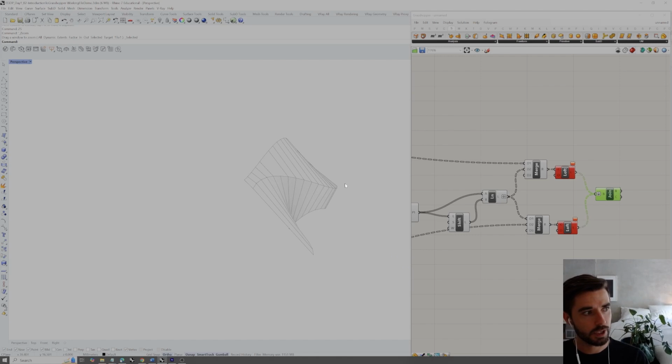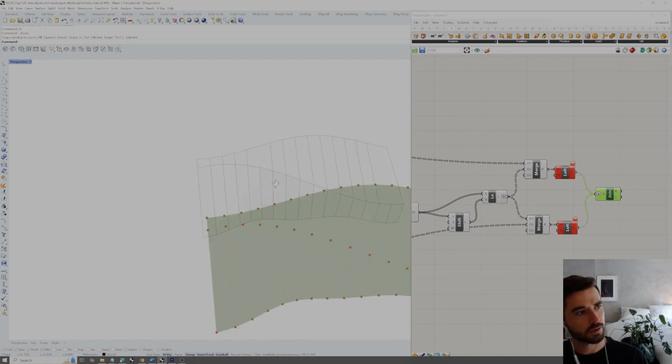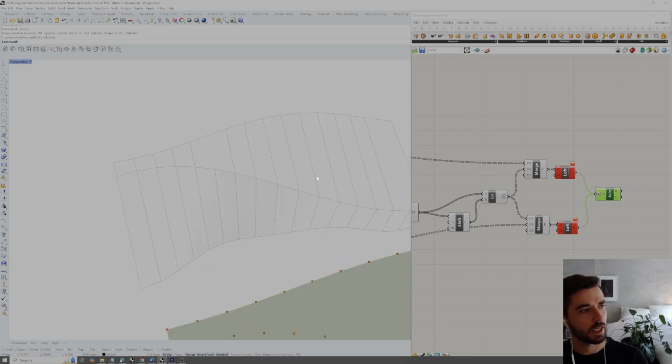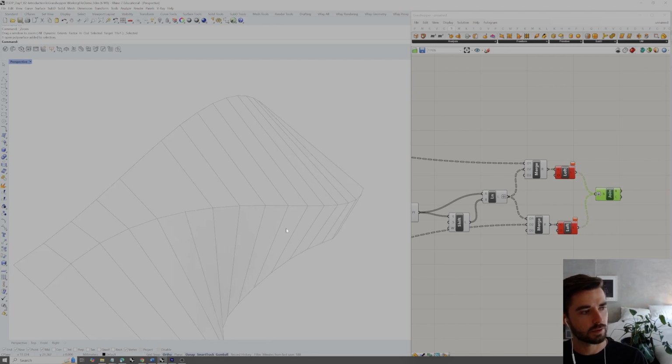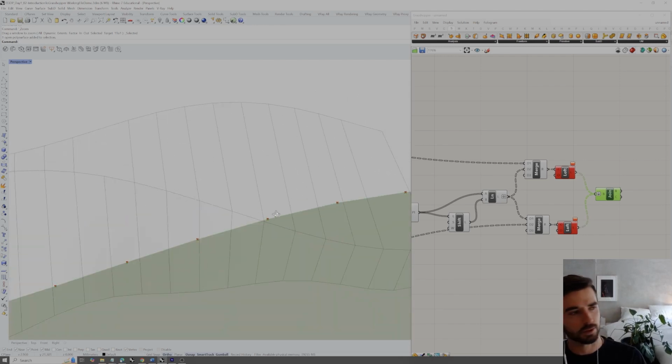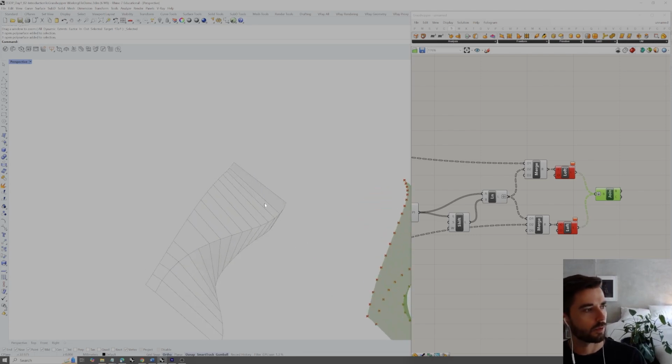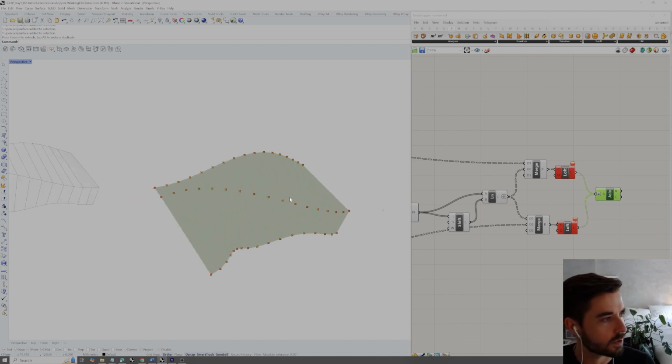So that's much cleaner. We have a crisp edge in that midsection there. So much nicer than that first set of lofts that we had. It keeps the cleanliness of the geometry, and we only have twisted surfaces, but singly curved ones based on ruled surfaces, which is really nice for fabrication. So we can go ahead and leave this over here just to remind us where we started.